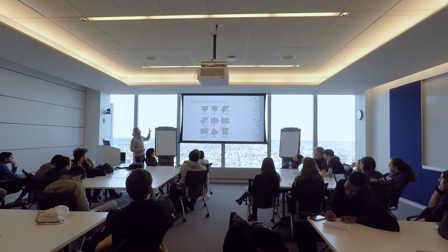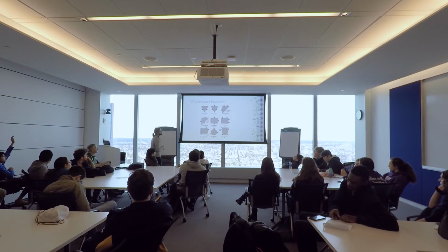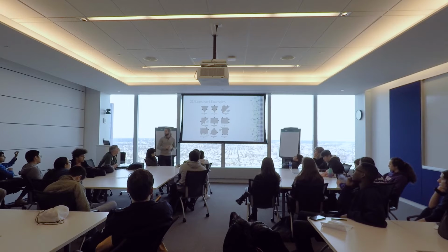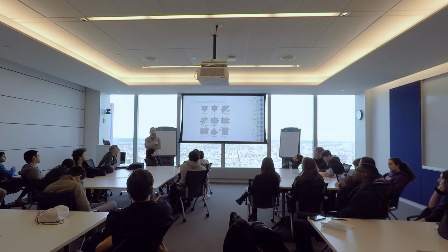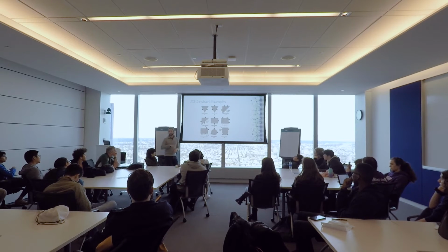These are some quick 2D constraint examples just for people that aren't familiar with fully constrained systems, to try to picture in real life how this would be constrained. Sure. How is number one under-constrained? That's a great question. So number one, if you had this triangle on a piece of tape, on a table or whatever, and you had these 2 pins in place, do you agree that this triangle could be rotated in that position? That is one of the degrees of freedom. It's not fully constrained because it can rotate. All right.